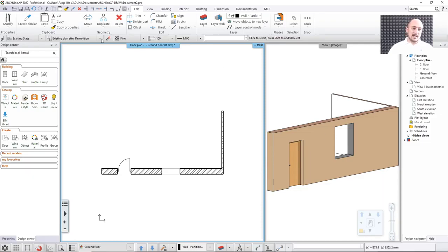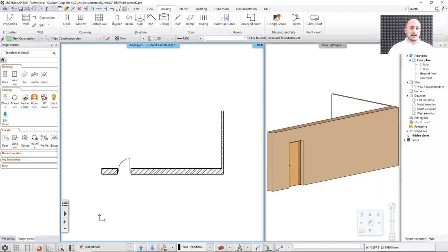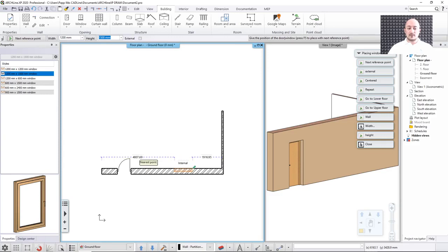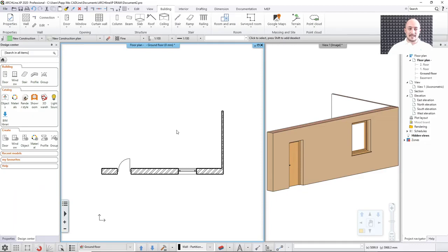And then when you move to the final phase, which is the new construction, you will see that the software will autofill the wall, make it ready for receiving any sort of other wall connections, or perhaps a new window. For example, in this case, if I just go here and say I would like to place the same window which I placed before, but into another location, for example to this point, then now I have a version of this plan in the same exact project without switching to other drawings or something like that. In the same design, in the same floor plan, I have 4 different stages of this building. The final, where parts are removed and there is a new window installed.